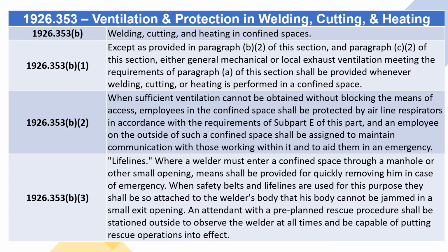B.3. Lifelines. Where a welder must enter a confined space through a manhole or other small opening, means shall be provided for quickly removing him in case of emergency. When safety belts and lifelines are used for this purpose, they shall be so attached to the welder's body that his body cannot be jammed in a small exit opening. An attendant with a pre-planned rescue procedure shall be stationed outside to observe the welder at all times and be capable of putting rescue operations into effect.